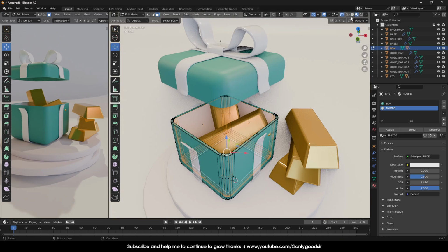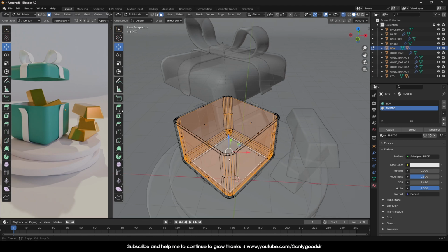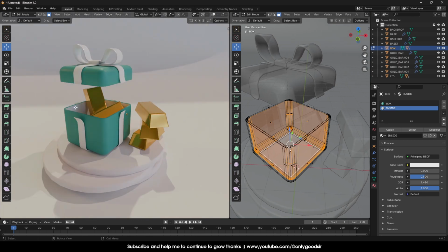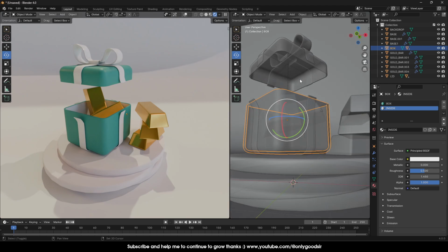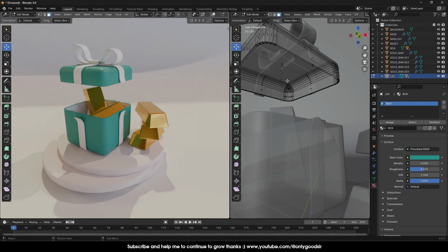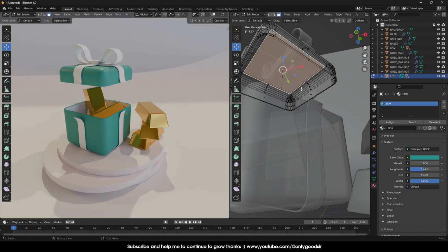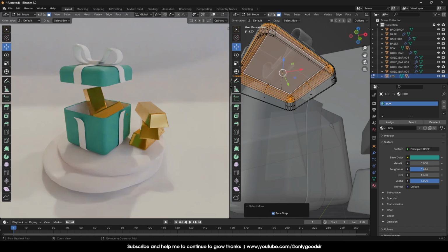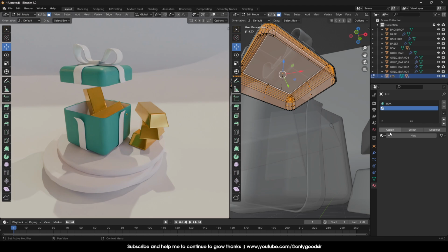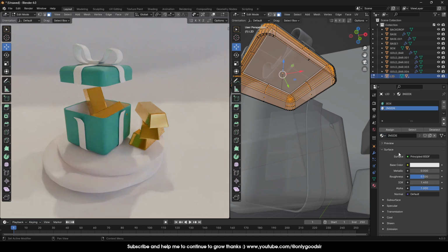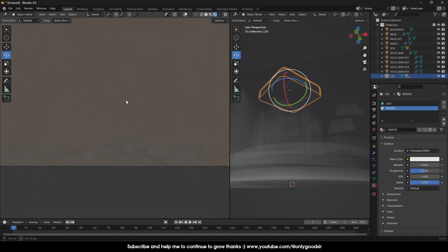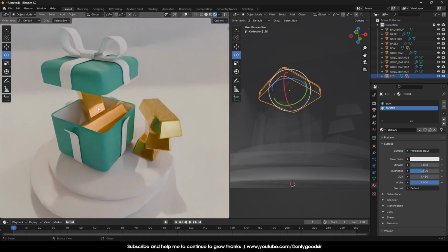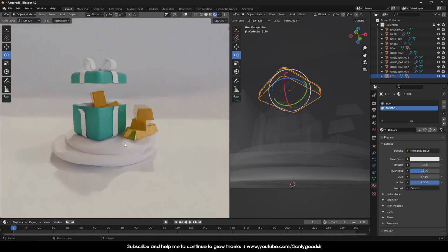So now you should be able to see here, it's a different material now. And again, we do it the same on here. So just select this face on the inside, Control plus to grow the selection. We're going to assign a new material, plus assign a new material, which will be inside. There we go. Take a look, you can see now we've got an inside completely different from the outside.